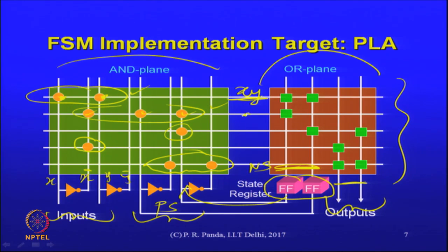So, that is the meaning, and so product terms are formed, and you select from the AND plane of the PLA which lines you want, and the complemented versions are also available, so that we can form any expression. But these are all individual AND terms. There may be as many literals, as many variables here as the number of connections you make there. So, that is what these are.